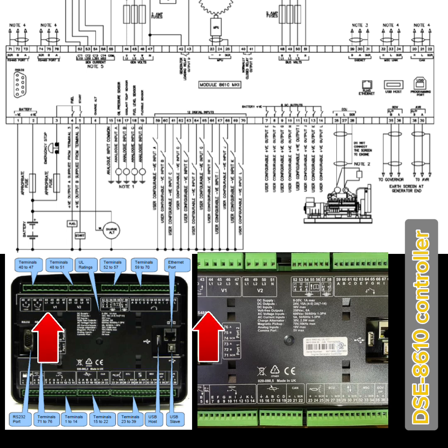Next we will discuss all the upside terminals. Upside, here are terminals 40 to 47. Numbers 40 and 41, you can use these two wires for the normally closed relay output. This is a dry contact. You can use this dry contact for your breaker or any configuration. And the next, 42 and 43, is a dry contact, close and open. This is the generator loading relay output D. You can connect your dry contact points here.